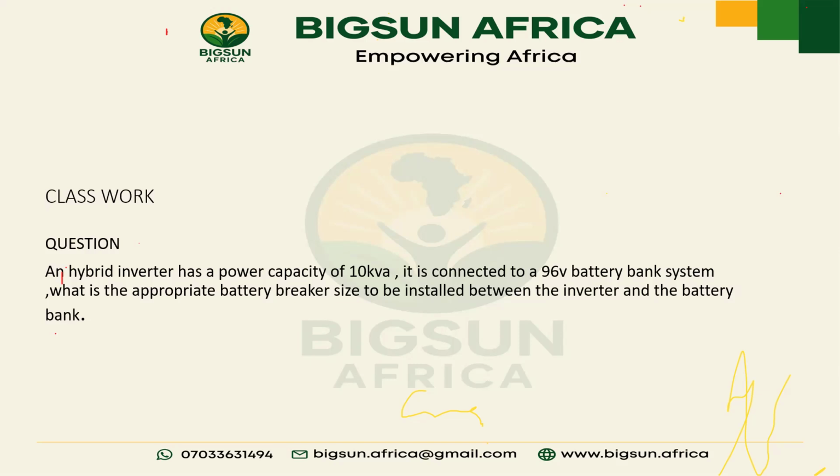So you are saying that most 10 kVA inverters, the real power is 8,000 watts. Exactly. But I've come across an inverter that is 10 kVA, and from the inverter specification the real power is also 10,000. Is that still possible? Some inverters have a power factor of 1.